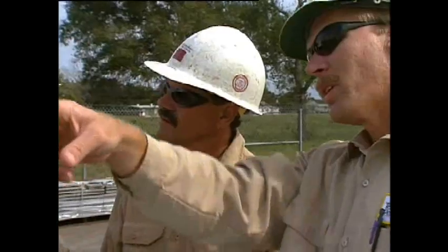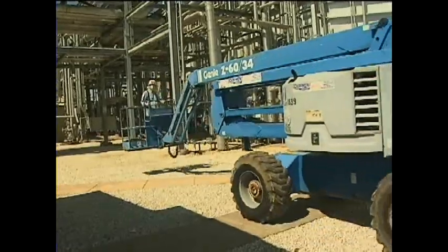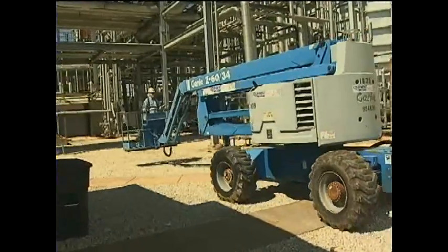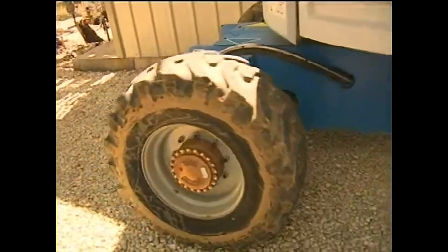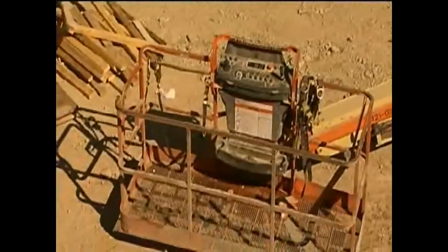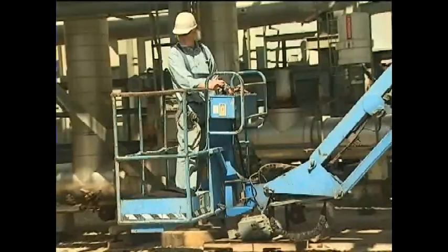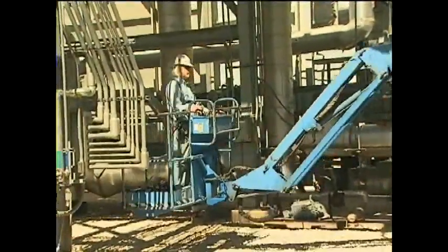It is necessary to always inspect the work site prior to using the lift. The ground on which the lift will be used needs to be solid and as level as possible. Do not use a lift on unstable ground. Hazards that may create dangerous driving conditions, such as overhead power lines, holes, drop-offs, bumps, lumber, tools and debris must be identified and procedures to avoid any hazards made known to all employees.